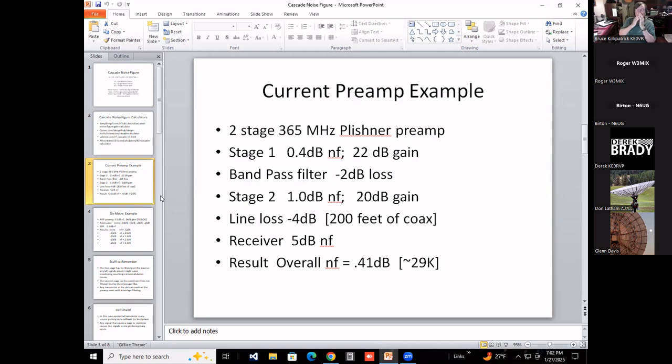Say, Ray, this is Bill. Let me ask a couple of dumb questions. Does the bandpass filter have any noise figure? No, it's just a loss. It does not have any gain. Ideally speaking, they're lossless components. They're capacitors and inductors, and they're lossless, but in real fact that's not the case, though the loss is very small if you build them right.